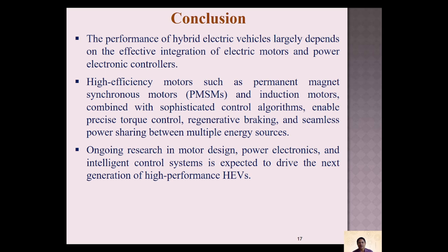In order to conclude on the drive systems available for electric and hybrid vehicles, the performance of hybrid electric vehicles largely depends on the effective integration of electric motors and power electronic controllers. High efficiency motors such as the PM synchronous motor, that is the permanent magnet synchronous motor, and induction motors combined with sophisticated control algorithms enable precise torque control, regenerative braking, and seamless power sharing between multiple energy sources.